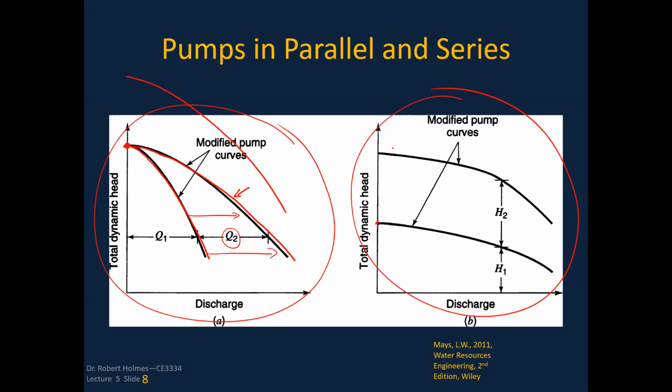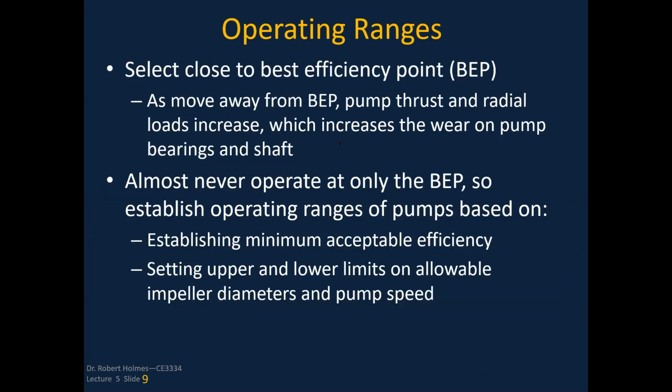With a pump in series, I'm not really adding flow for each additional pump. If I'm at this flow rate, I'm not really adding flow, I'm just adding head once I kick that second pump on. So this is pumps in series. These are pumps in parallel. So make sure you understand that.